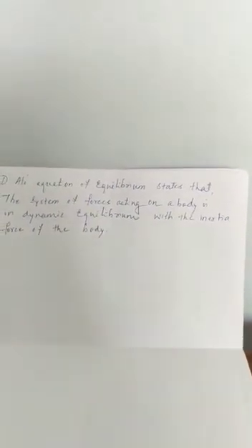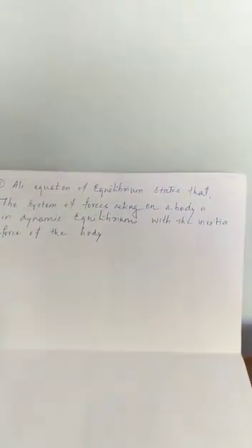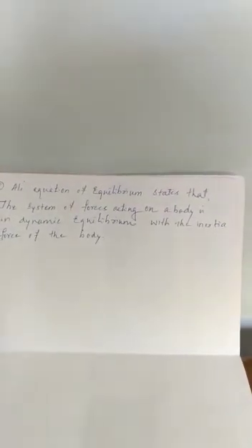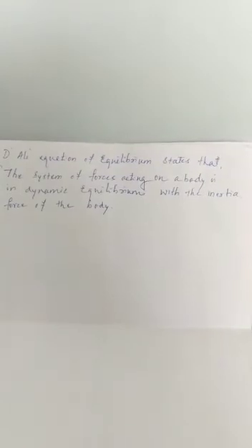The second aspect to consider is when the lift is coming down. The external agency is slowly letting it go; the entire weight of the lift acts downward, and the force from the cable at the top acts upward but is slowly leaving it. If you think of the free body diagram of the lift, the net resultant of the forces acting on it is in the downward direction. That's why the lift is moving down. But at that time there is an inertia force opposing it, acting in the upward direction. This is the overall concept of D'Alembert's principle.